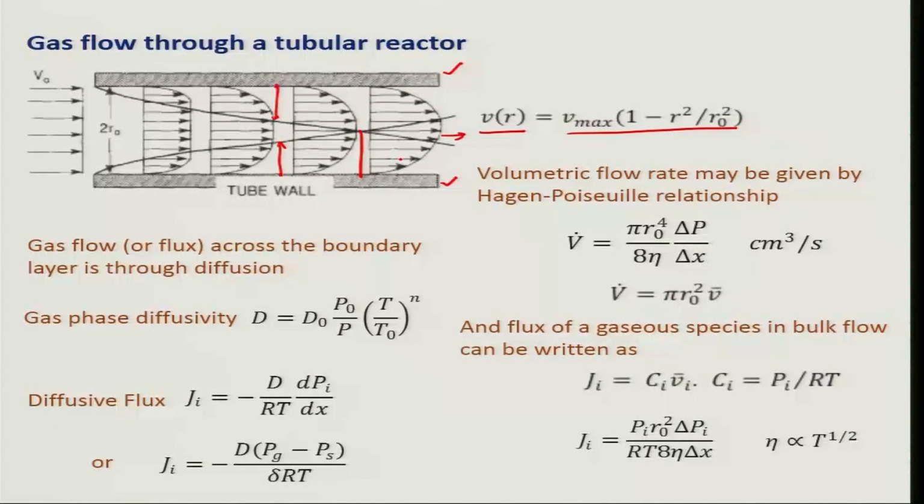If we are designing our tubular reactor for chemical vapor deposition, we should make sure that this is not my reaction zone, because the flows are not stable. There are different flows and the boundary layer thickness is different, but beyond a certain distance the boundary layer thickness will remain constant, and we can use this region for uniform deposition of the film.